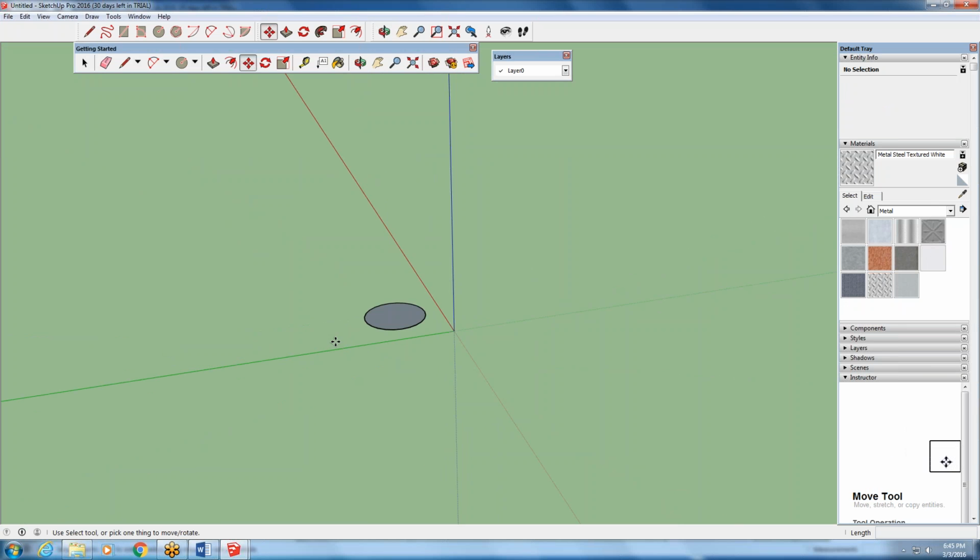Okay, it says, take a look at the color palette in the first image. We're drawing a line parallel to the red axis, so we would say we're drawing in the direction of red. We know that the line we're drawing is parallel to the red axis because it turns red. And in the second image, we're moving a box parallel to the blue axis, so we're moving in the blue direction. We know parallel to the blue axis because of the dotted blue line.